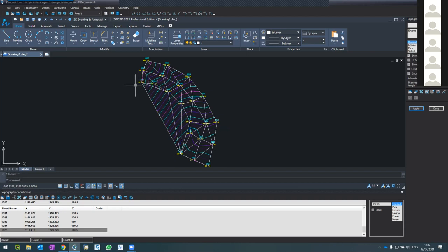So again, the problem of the borders is where our surveyed area is not convex. It has a road, it goes like this. Or in other cases, you'll see it as well. And the software automatically interpolates to the maximum coverage area. Although we know that the contour lines end up here, the software continues with additional triangles, which we don't want. So this is the border problem.